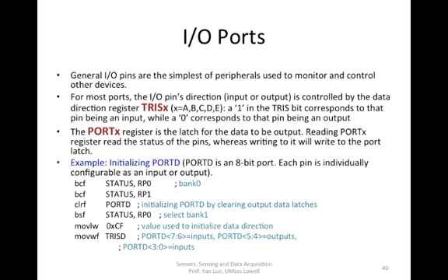Okay, this slide is talking about how we do the I/O. I touched upon it a little bit. We talked about using a register from bank 1 to tell the PIC how to use the pins, and a register from bank 0 to get the data in or out. Coming back to the I/O, we do the same thing. For any I/O port, A, B, C, D, or E, we have basically 2 registers we use to either control the operation or manipulate the data.